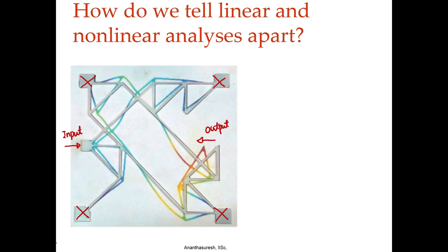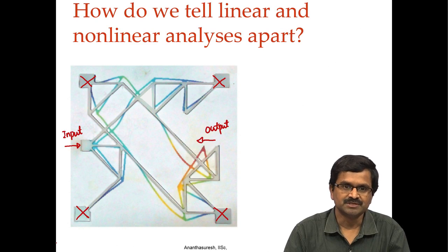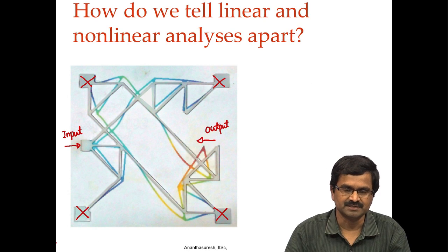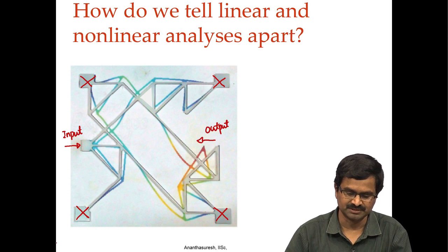We had started the last lecture with this question: when I take a real compliant mechanism and analyze it using finite element analysis, be it your own code or any commercial finite element analysis software, how can we tell apart linear and nonlinear analysis? It is really important, because compliant mechanisms do undergo large displacement, large rotations and a lot of nonlinear behaviors when we use them in practice, and that is very important for us to notice.